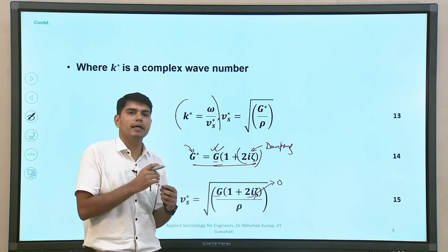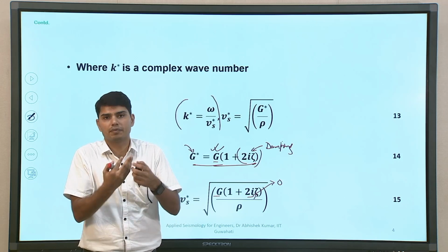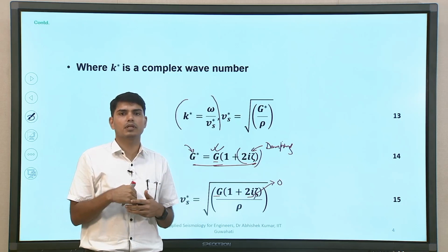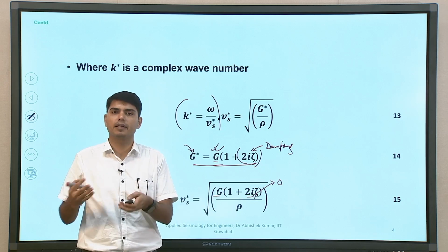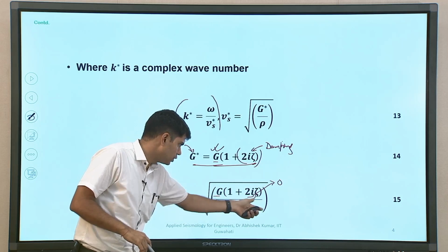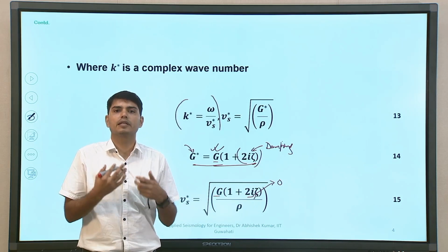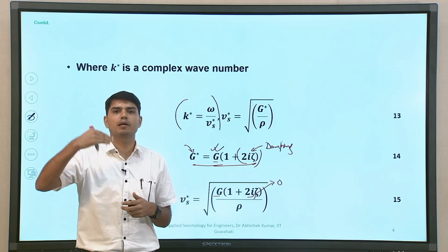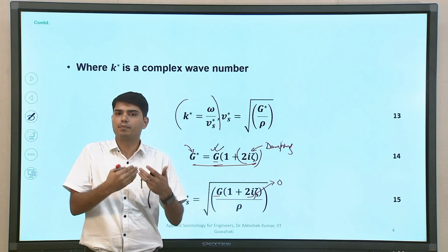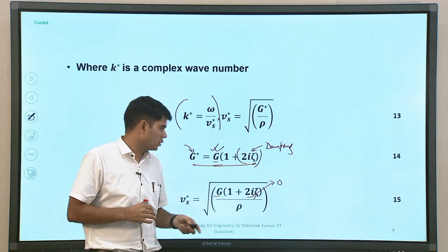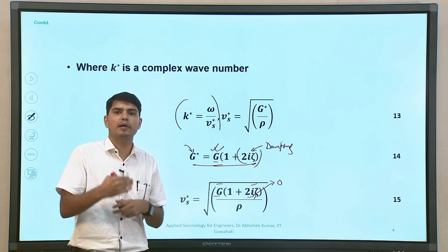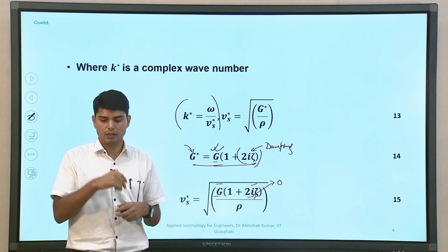That means, if some earthquake is mobilizing a very small value of shear strain in the soil, the same soil may behave differently in comparison to another earthquake which induces a different value of shear strain. Certainly, the local site effect will be significantly different even at the same site. For that reason, many times even when an earthquake has happened at a distant location, because of these two properties collectively, the resistance the soil offers is significantly different, leading to amplification of the bedrock motion, and subsequently this amplified ground motion is subjected to buildings. These will undergo failure. The ground, if possible, will undergo liquefaction even at larger distances. That is primarily because of dynamic properties, which are not constant for a particular soil layer but dynamically change depending upon what external loading condition, what shear strain is being mobilized in the particular soil layer.